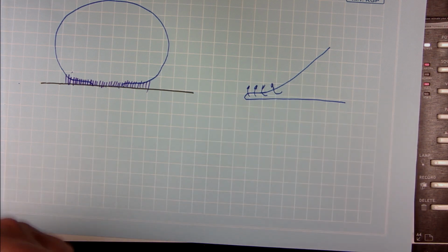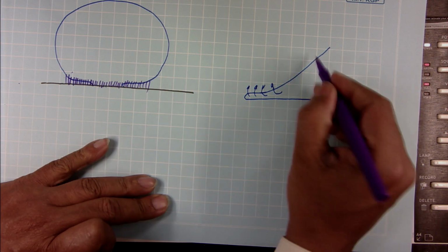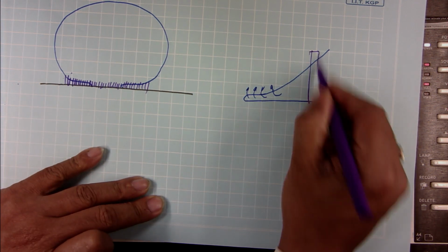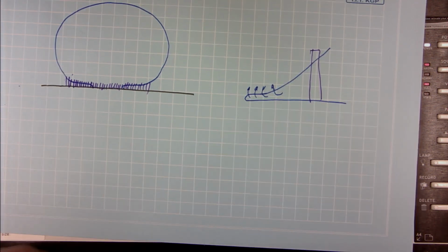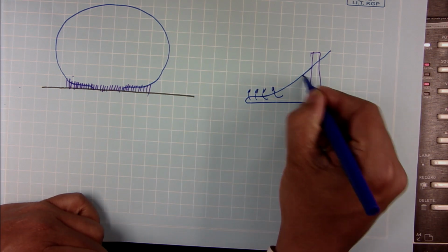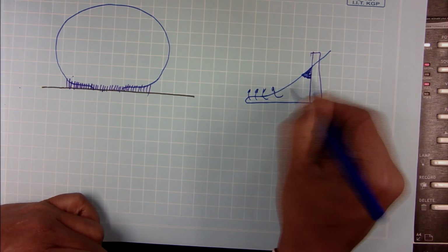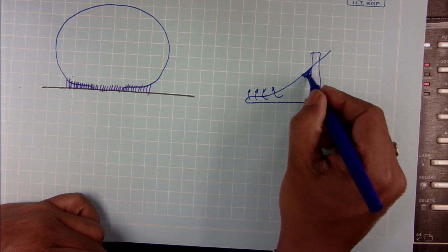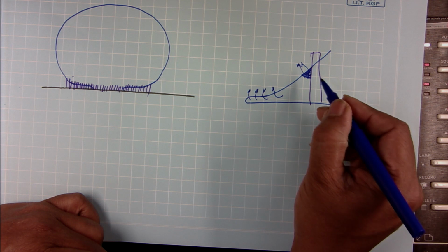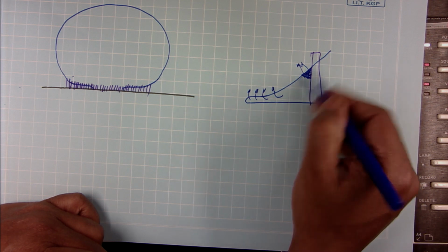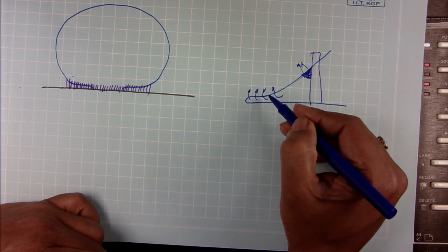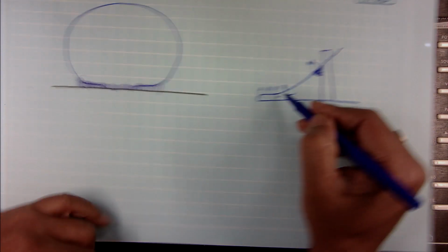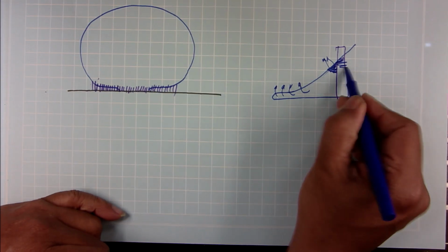And the moment I have formed a microfin or a nanofin that is sticking here, I am forming that same dynamics here also, because I have a wedge of liquid trapped here, which is also of the order of 100 nanometers. So I am causing a thin film evaporation here as well. Okay. So these zones of thin film evaporation have increased, that is one part, and then the second part is only the first 100 nanometers is participating.